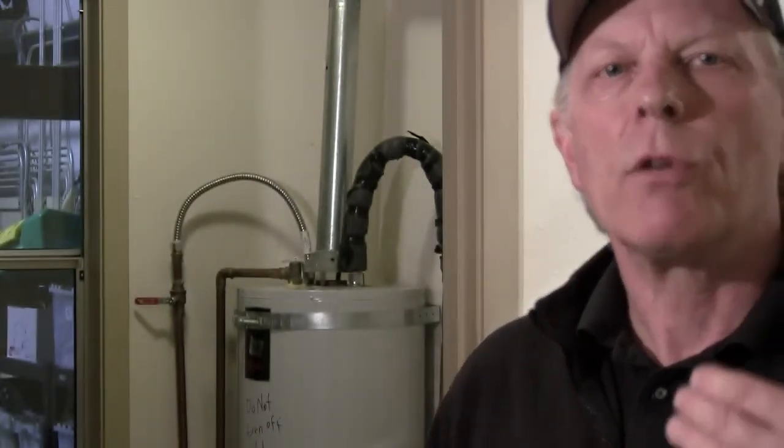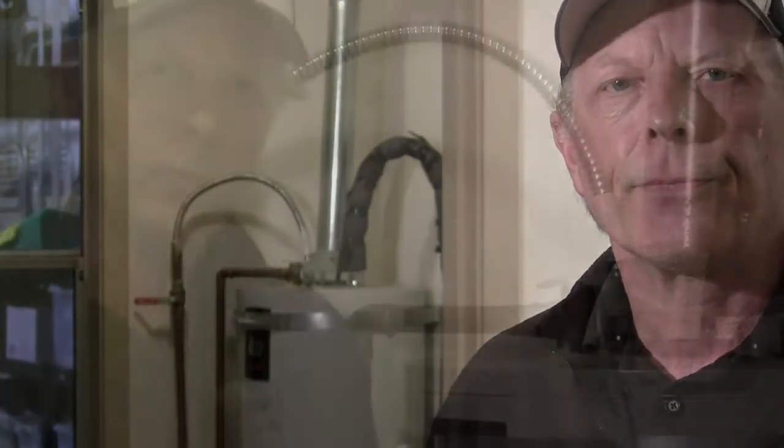Once we turned the fans on, we got to about negative 3.1 to 3.4, and that didn't change once we turned the air handler on, and it didn't change when we changed the door position. So what caused the greatest depressurization in our combustion appliance zone is the exhaust fans.